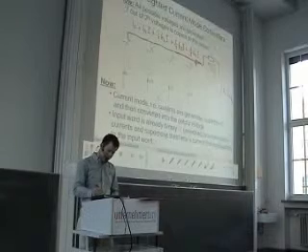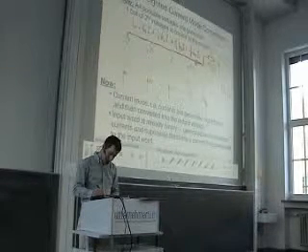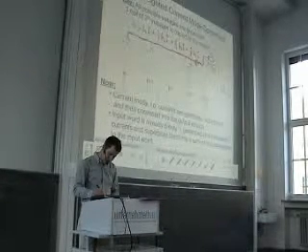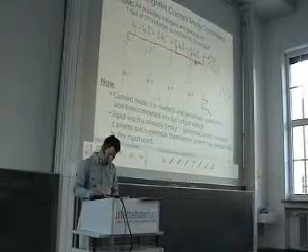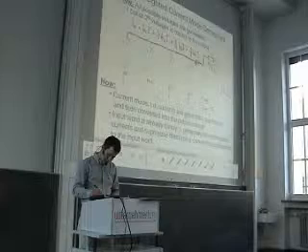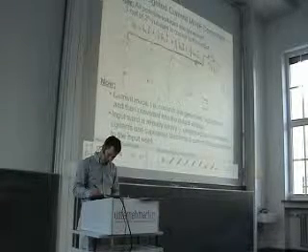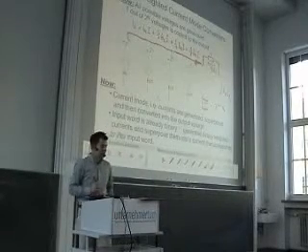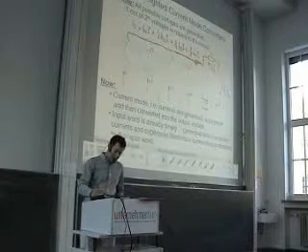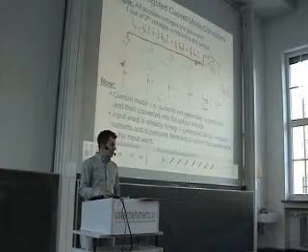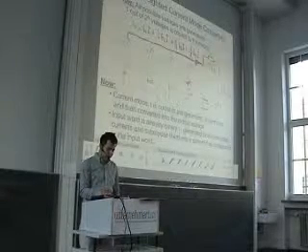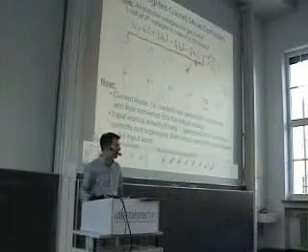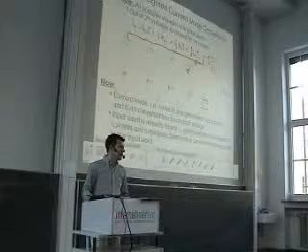You can see that we have a ratio of the maximum current to the minimum current equal to 2 to the power of n minus 1. So here the current is much bigger obviously than the current here. So also the symbol for the switches is the same for all of these current sources.